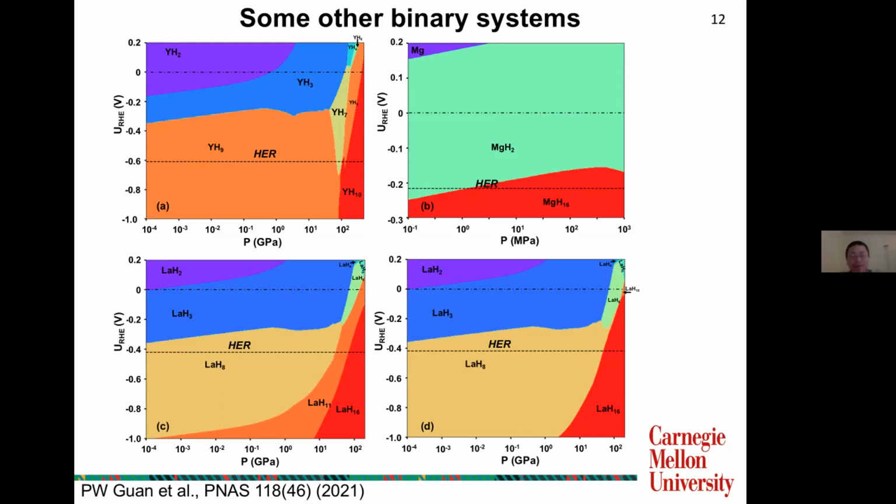Yeah, I haven't considered kinetic effects in these diagrams. All these are thermodynamics. Actually, because you change the type of the metal lattice, it will involve the breaking of the metallic bonds, so I think this will have some kinetic barrier. In practice, increasing the temperature will help you overcome the barrier. Another point is that maybe in practical products, it's not equilibrium phases. Actually, some are metastable, but the kinetic barrier is smaller.